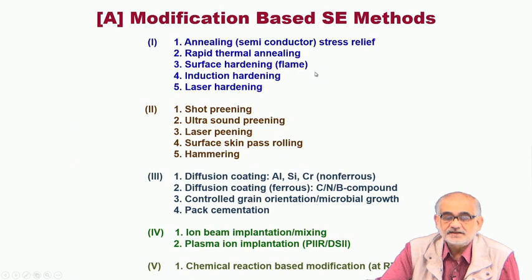In case of steel, a very routine and standard technique is to harden the surface by heating it either by flame or by induction, electromagnetic induction, or even using an electromagnetic wave called laser, so that the surface, from the top unto a small depth, gets heated up. Within a very short time you apply a pulse heating, because of which the surface gets